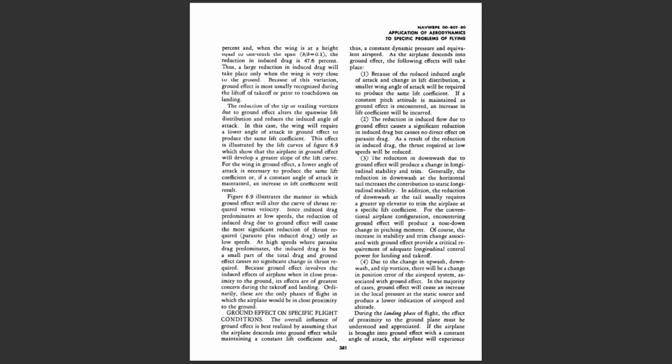2. The reduction in induced flow due to ground effect causes a significant reduction in induced drag, but causes no direct effect on parasite drag. As a result of the reduction in induced drag, the thrust required at low speeds will be reduced.